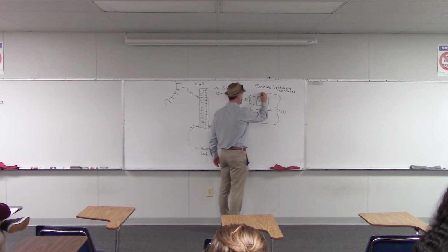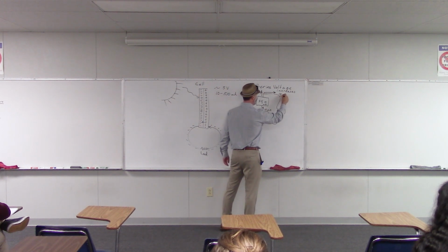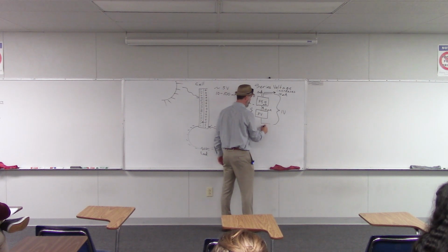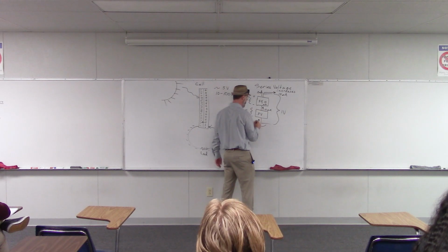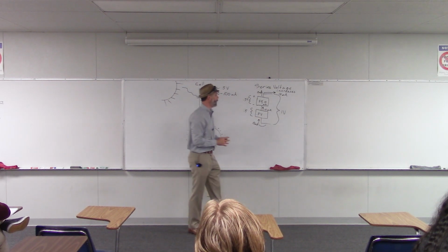And then the second one would have 10 milliamps flowing out. So altogether, you'd have 10 milliamps flowing out of your circuit, and then it would go through the load and come back, so you'd end up with 10 milliamps flowing back into your circuit as well.